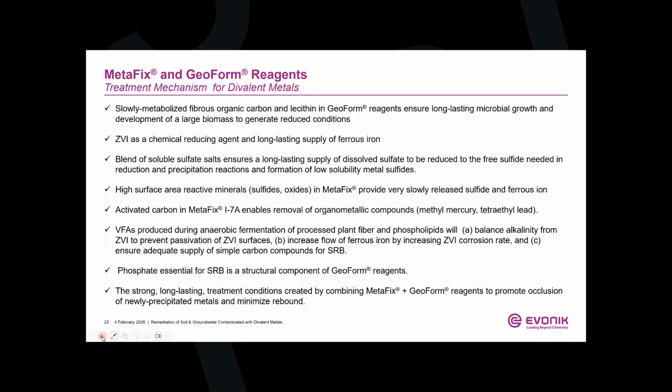So to review, and I won't go over this line by line, but just to say the formulation of these reagents will give you the reducing conditions you need, the ferrous iron you need to promote profuse precipitation of iron sulfides to lock up the precipitated heavy metals, a good environment as far as pH and free sulfide to precipitate divalent metals as divalent metal sulfides, which are almost insoluble, and they're pH balanced so that you won't go outside that optimal range.